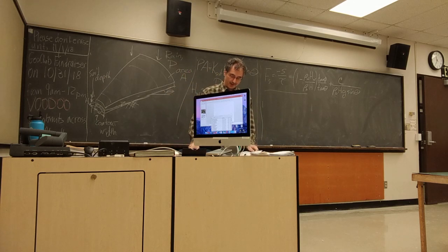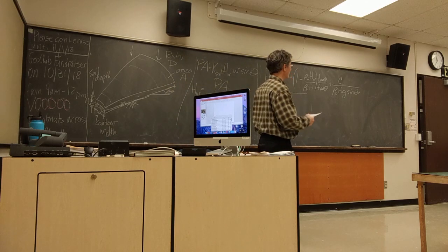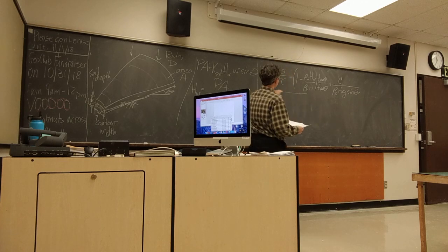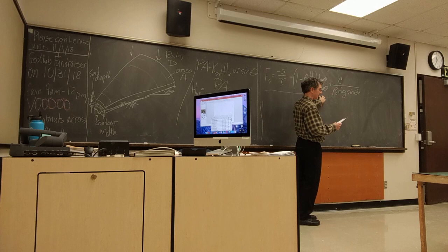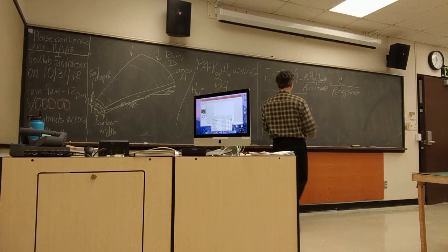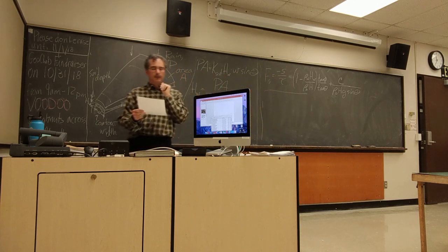So if I get a little exercise about this factor of safety stuff, it's because it really does matter. We can actually learn some valuable stuff. If we wanted to be real sure of stability in this case, then we'd just set cohesion equal to 0 and set that equal to 1 and run away with it that way.